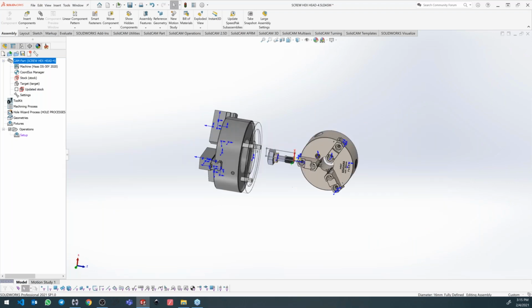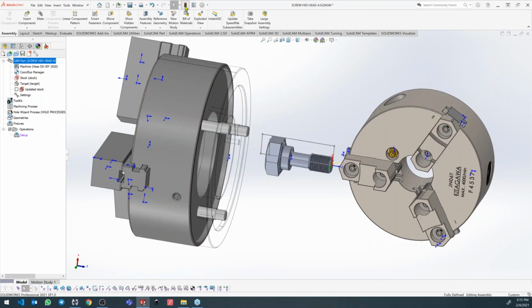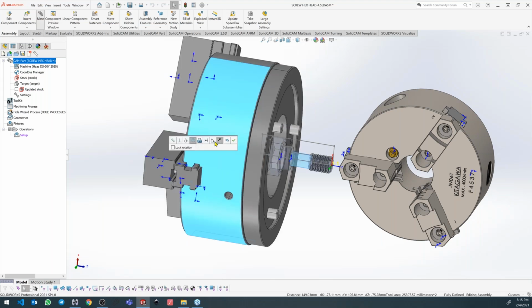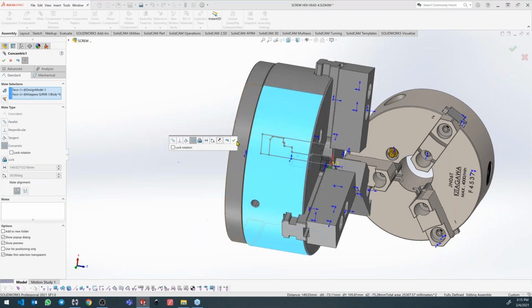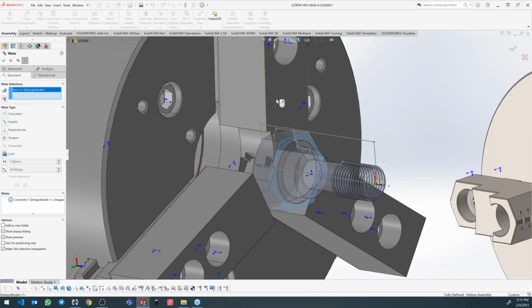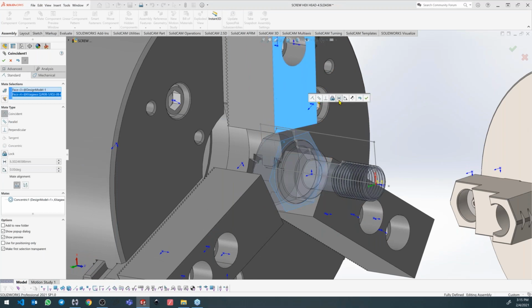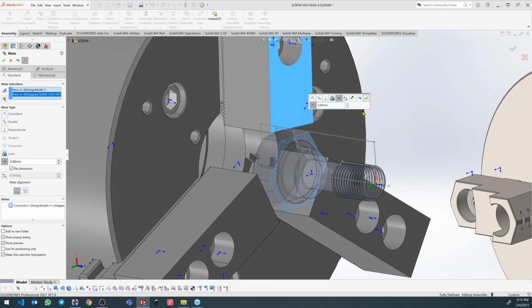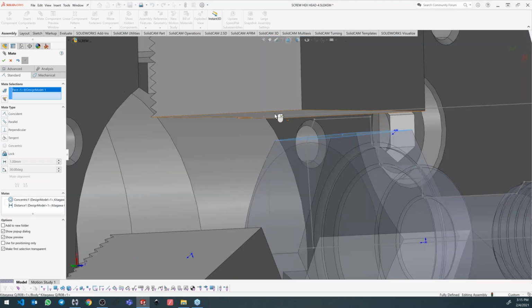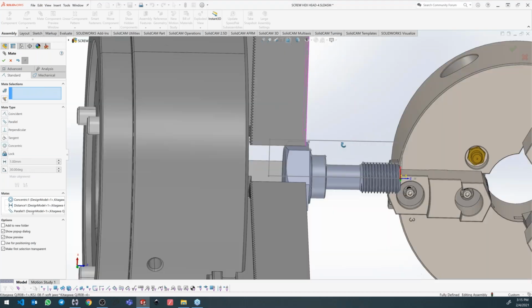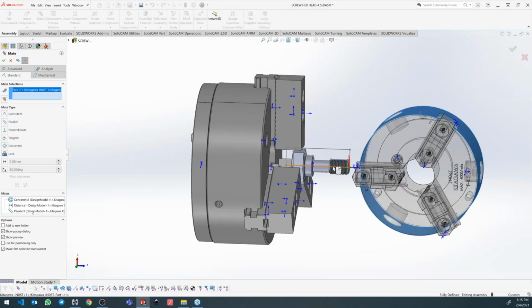Okay, I'm using my mounting tool to make a mounting of fixture relative to part. Reverse it. Okay, we'll make a dimension here. Okay, let's say 3 millimeter. Okay, I will make it parallel. So the first chuck is ready. I'm going to make a second.